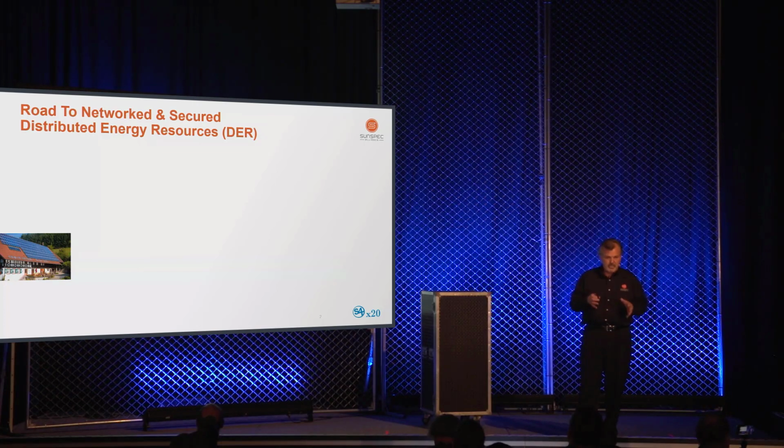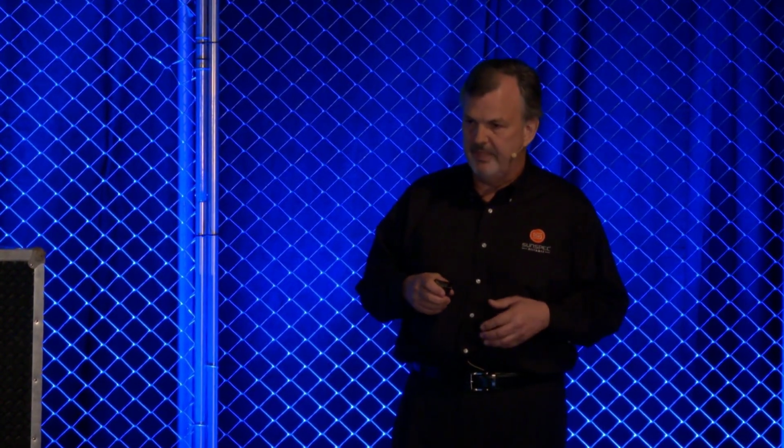With these high concentrations of distributed energy resources on certain feeders, what happened is, given the rigid grid control standards of the day, Germany encountered this problem that's now known as the 50.2 hertz problem. Once the inverters hit that threshold in high concentration areas, they would trip off. And so you'd have large portions of the network just simply disappearing.